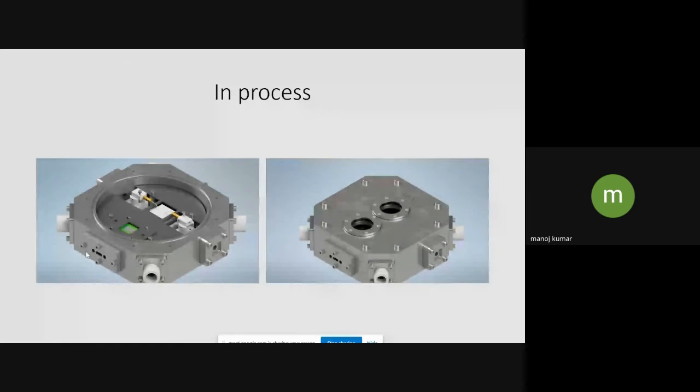But let's say I am making a solar cell also. So this system combines both things. The stability setup, that is the green one, is your stability setup, and this is your 2-probe setup. Most solar cell characterizations are done in a 2-probe setup. If you need, let's say you are making a thin film of metal and you want to do a 4-probe measurement, we can also integrate two more probes in this case if someone requires. So this is from my side.